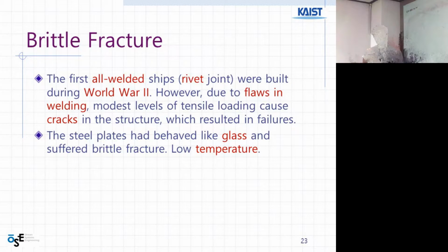And there's one more thing: the parts that are close to the neutral axis are not under stress. So this is a serious problem for many cross sections, like circular or rectangular. The problem is that these cross sections use the material inefficiently, and many parts do not contribute to resisting the stress.